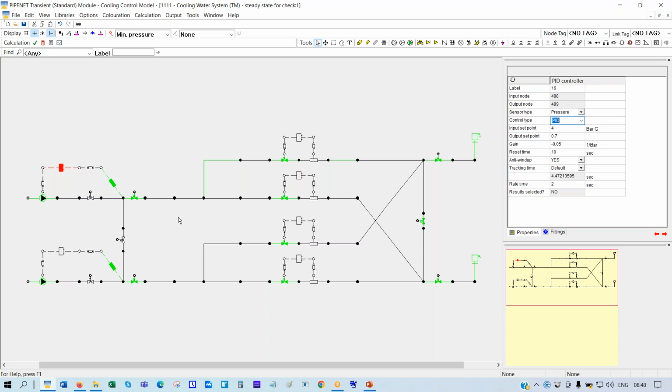But the fluid says, no, you're not going to stop, I'm going to keep you moving. So you see, as a result of that, you get vacuum pressure in the pipes, and that vacuum pressure can make the pipes collapse when you have such large pipes and there is pump failure.